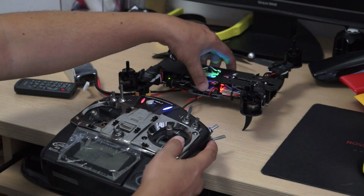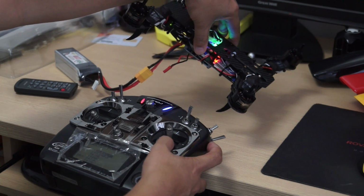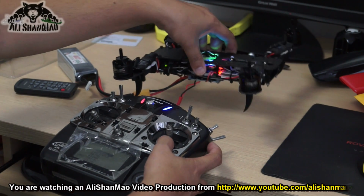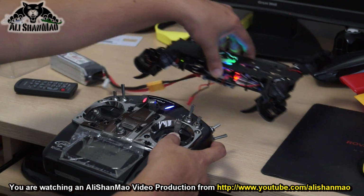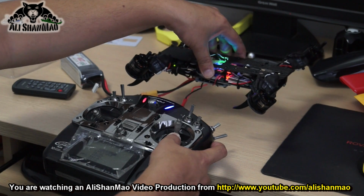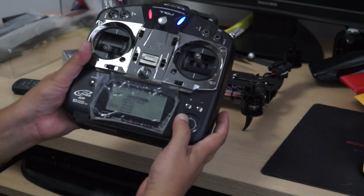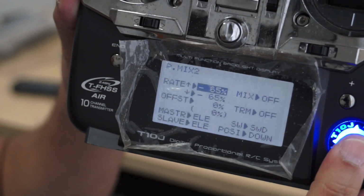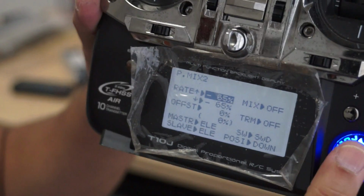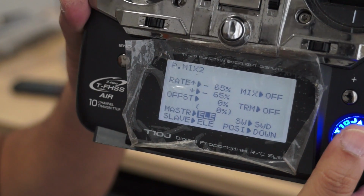So what we want to do is reduce this tilting effect on the elevator, and we just want the quadcopter to tilt a little but the motors tilt more, so that the quadcopter will be leveled and pick up the speed due to the rotor tilting. I have described this concept before. So what we are doing here is creating another mix which is called elevator to elevator. What we are doing is simply setting the master and slave elevator to elevator channel 2.